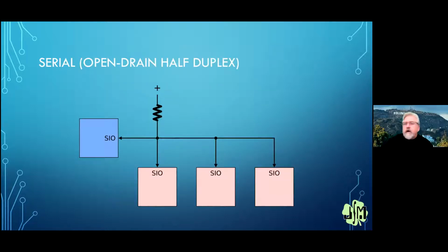Here's that setup I talked about for like the HC8 and other cases where you want to have microcontrollers talking on a single wire. This looks very reminiscent of I2C, right? Where we have an open drain or open collector setup. So we're going to have a pull up, which is pulling the line to the idle state. And then anything that wants to talk will create a 0 bit by pulling the line to ground and then releasing it to the pull-up for a 1.